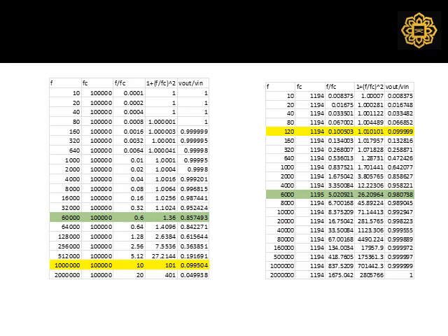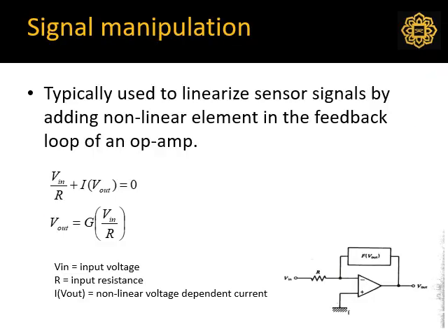Then if you do a plot, you can see the same thing. You're losing a signal to 0.86, and this is 10%, and 120 and below is less than 10%, and here you have 98% at 6K. So from 6 to 60K, you still have 98 to 86% signal. And at 1 megahertz and above, you have 10%, less than 20%. So this is how we can say that we have designed a band pass filter. Okay, so these are the filter problems that can be asked in the exam.